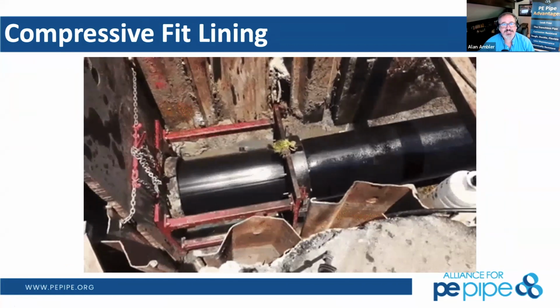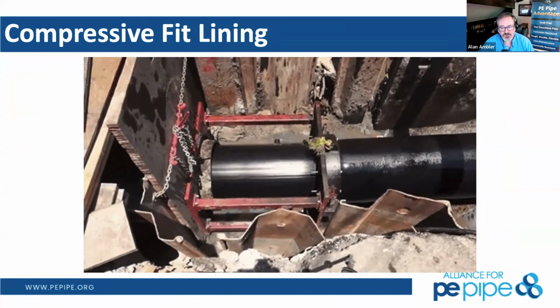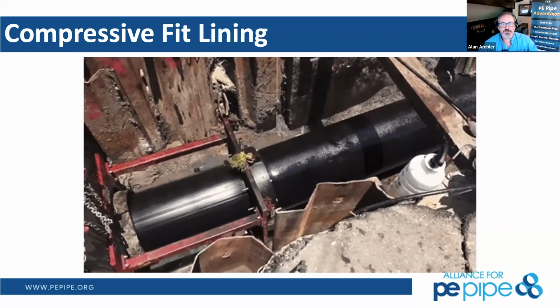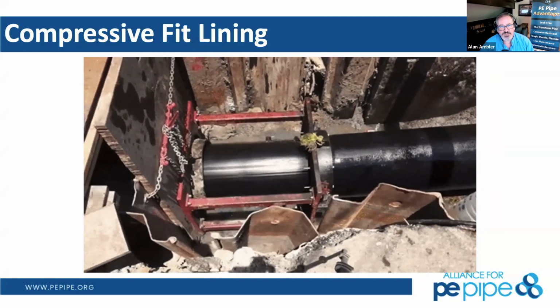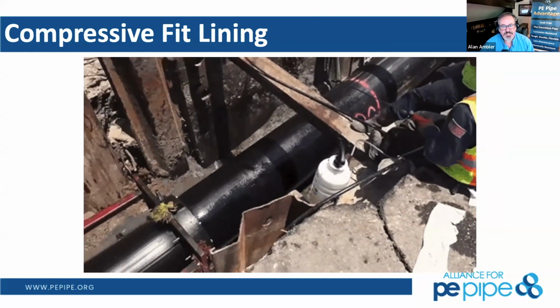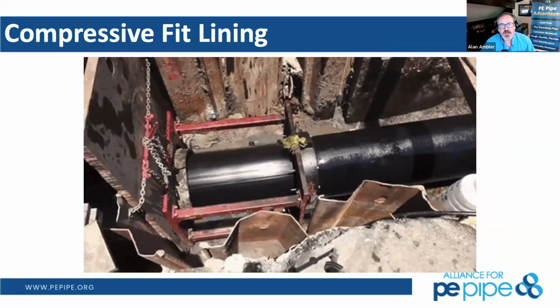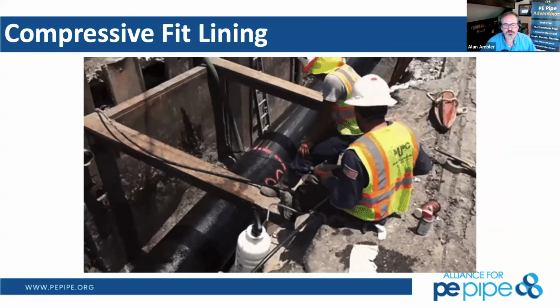Most of that relaxation occurs, of course, in the 2 to 24 hours surrounding it. So for engineers that are conservative, we always want the largest ID we could possibly put back. If you absolutely have to have that, then you would look towards compressive fit slip lining in this application. So the forces, of course, are greater. You're going to have to be able to resist any urge for that machinery to be able to push through the soil column as we go through.